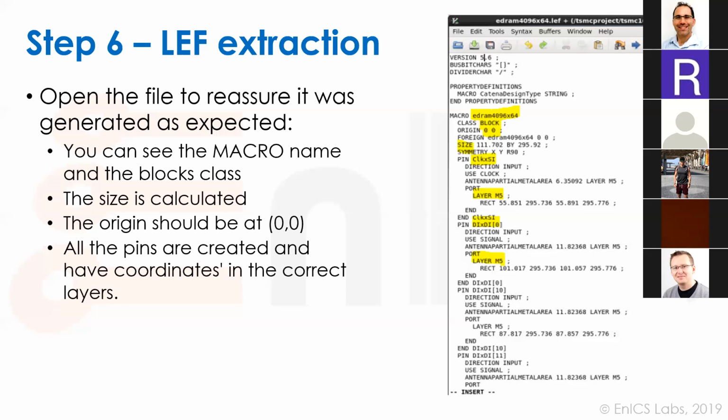Then you can totally ignore the lib file and build the LEF based on Verilog, by the way. Yeah, but you need the lib file for integration in the end in any case. Yes. As far as we know, I haven't heard anything different from Slava, but I don't even know if in synthesis you can always include the netlist.